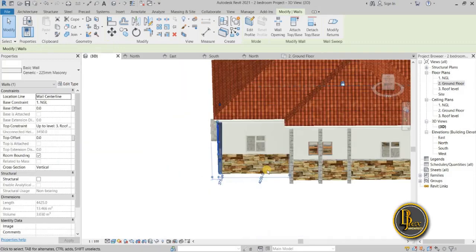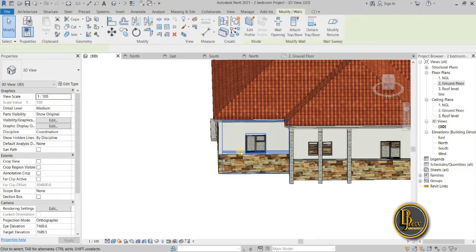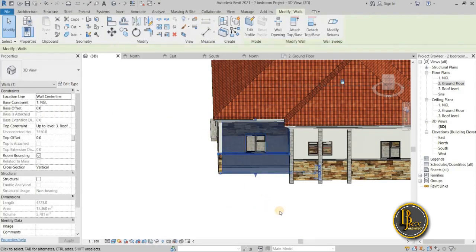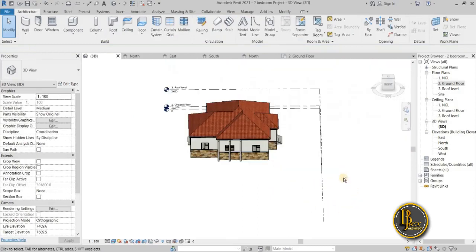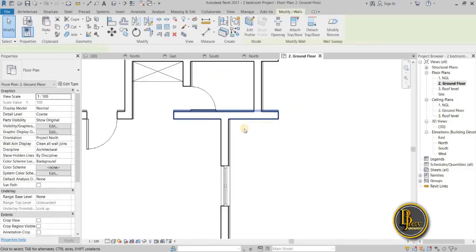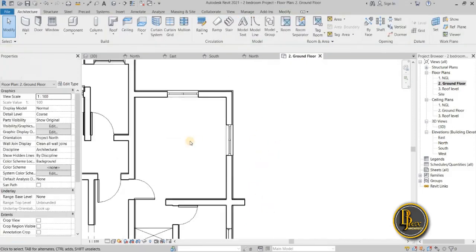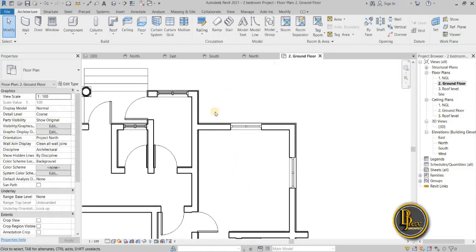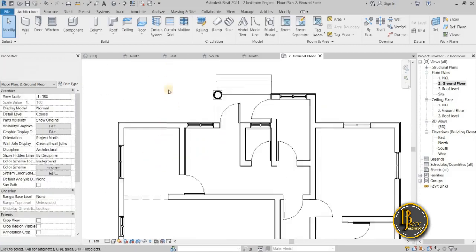Okay, it's not here. Just click here, click the wall, then press space bar and you flip it. So that's one way to do it. If you prefer working that way, you can also work that way. So if you look at it on 3D, this one now is supposed to be a press space bar, flip this. So I think you'll see it better on 3D and it's faster on ground floor view, because you see everything very easily.